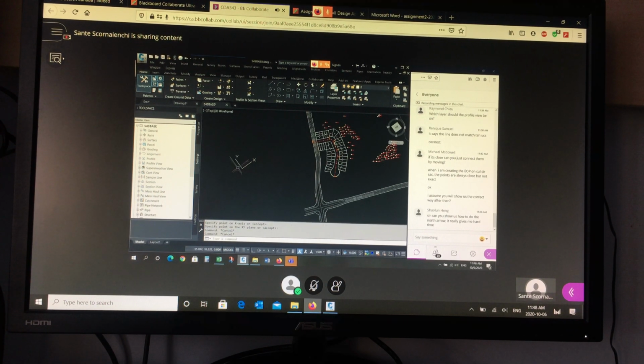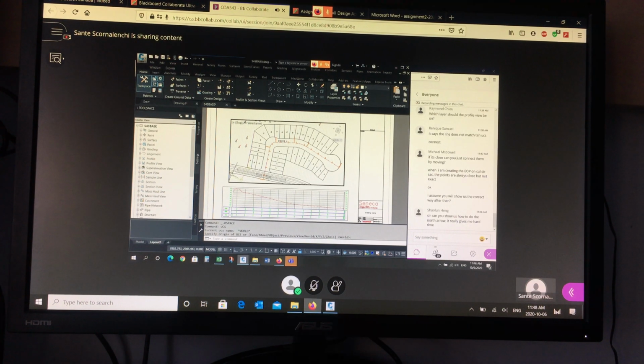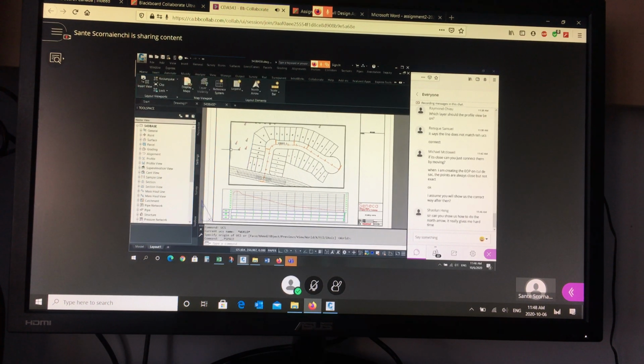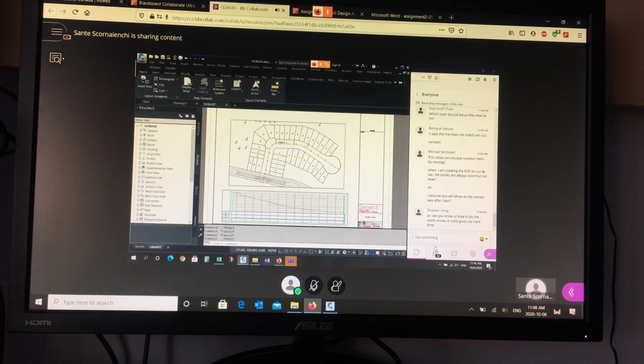So notice the difference is this icon has no little square in the origin. UCS, enter, enter. This one has the origin. So this is true north. So if you go into the viewport, this is not true north. Right? There's no little box. So I type in UCS and I hit enter twice. And now the positive X, that's the origin, in the direction of positive X, that's true north. So there's a couple of options for the north arrow. You could put the north arrow in model space and look at it through the viewport, or you can use the function in AutoCAD.